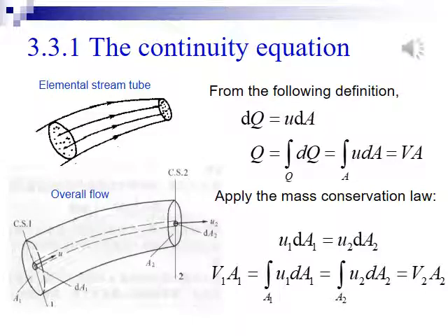For incompressible fluid, speaking in short, the amount that comes is equal to the amount that goes. Under the Eulerian method, that is, total upstream flow rate is always equal to total downstream flow rate. That is, for two cross sections in the stream, for example, CS1 and CS2, flow rate Q1 is equal to flow rate Q2, or in another form, V1A1 is equal to V2A2. It's the same with elemental flow.